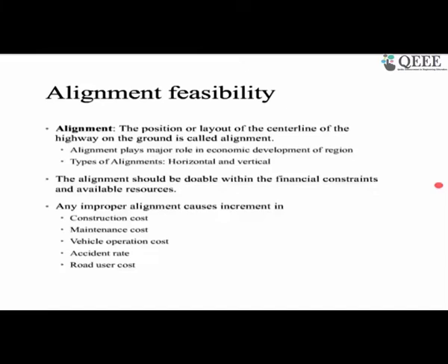But if you search, there are certain standards for how to do that. The other question is: an expressway has full access control, but an expressway which is passing through an urban area has no access control. Why is it called an expressway? As I told you, the expressway is one for the urban setup and another for the rural setup. In the rural setup, the speed is quite high, and it is for connecting distant places, so definitely there we need to have access control.